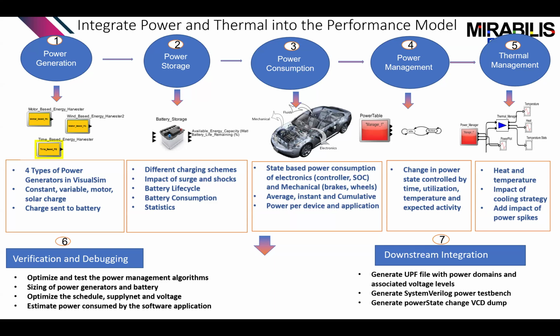We were looking at more of the hardware being modified, but we can also look at the management, where we don't turn on the power as soon as the requirement happens. We delay it a little bit, or as soon as it's done, we move down to a lower state. There are challenges there as well. For example, if you keep doing it too often, the transient time would end up being much greater and your performance would drop. When you do all of these, you want to see what happens to your heat and temperature, because that determines your cooling strategy, which means your cost related to cooling and your mechanical structure also changes.